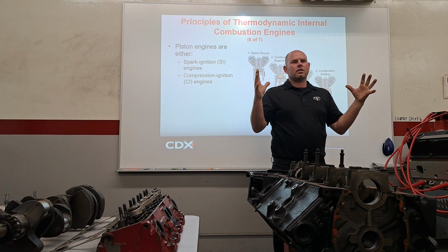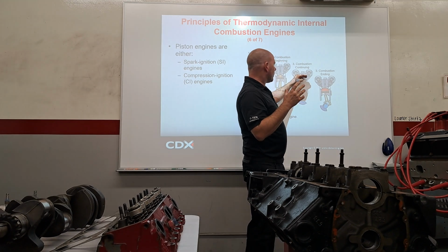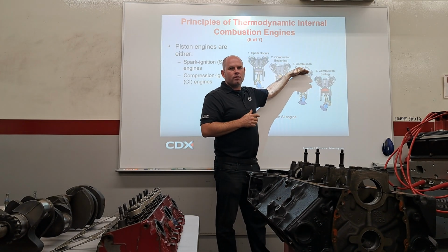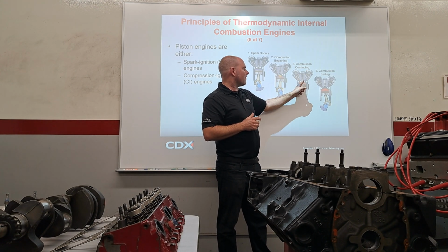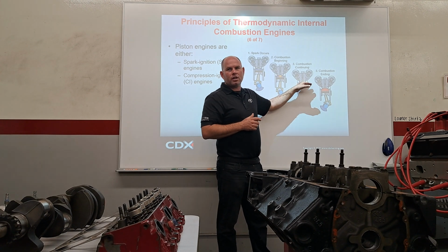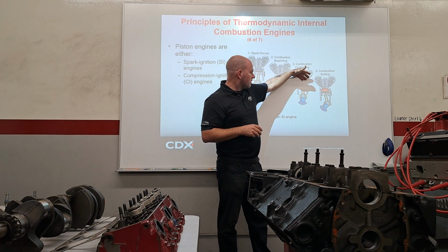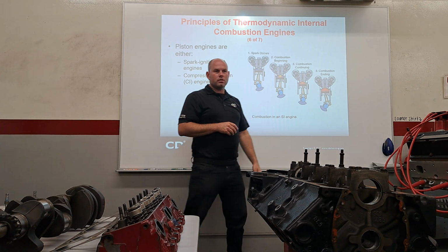If it's expanding, where's that expanding gas trying to go? It's increasing the pressure, right? So that pressure is trying to blow out the valves and the head gasket and all that stuff, but that stuff should be strong, so what's it going to do as a result? Push the piston down, exactly.